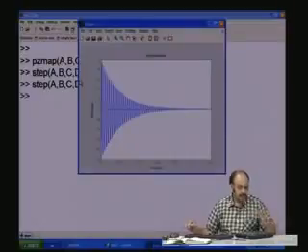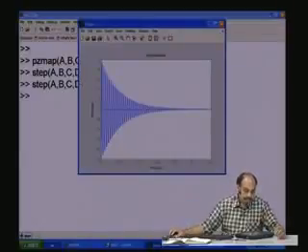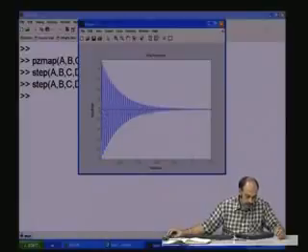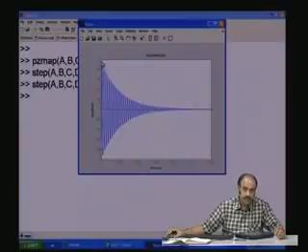So, let us see the step waveform. As I have been telling you, for a unit step input, you see the output voltage across the capacitance has an oscillatory nature, and then gradually it damps down. You see, the amplitude is gradually decreasing. This implies the loss in the resistor, and there is a time constant involved in that.